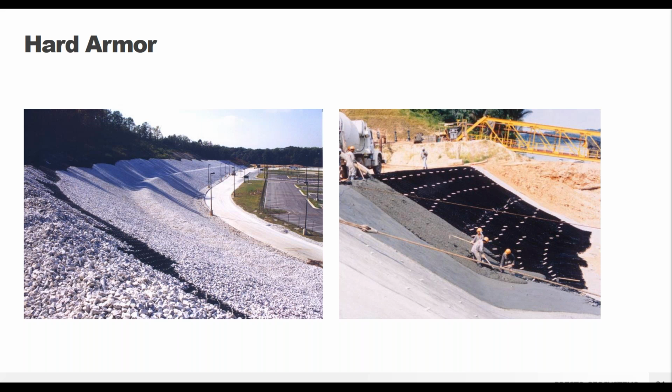And they can be installed in areas where you have really an arid environment, so you're not seeing a lot of rainfall, so vegetation might not grow. Or if you know that you need to collect your water from the slope and take it somewhere else, a concrete infill might be the way to go with that. So that's definitely an option. Definitely don't want to discourage you from that if it's going to be most appropriate for your project site. But yeah, vegetation probably the most common.